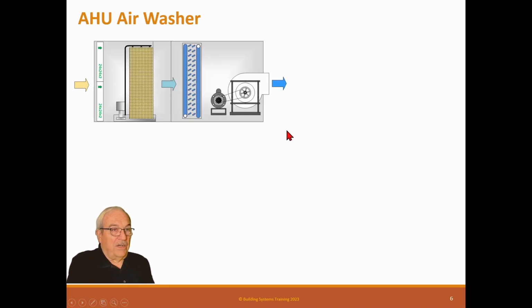All right, this is an air washer, which I was just talking about, which is a regular air handling unit, and it has an evap cooler pad in here, which is normally cell deck material. It has a pump and a pan, and it pumps water over it. Then the air goes to a cooling coil. Now, this is interesting. What happens is this coil ends up taking a lot of dry bulb temperature sensible out and adds latent heat to it, so it has more latent in it. And if that latent is too high, this cooling coil will actually take it out.